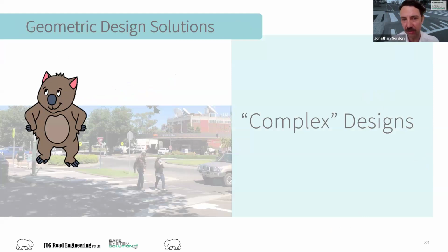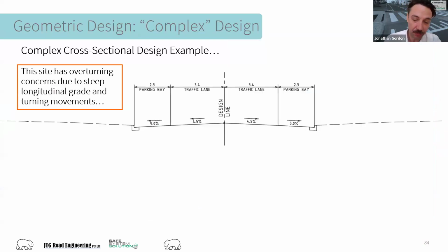We're going to have to change our longitudinal grade or our cross section to make this project work. That's when things get a bit trickier, but most of the time we can resolve these issues. And occasionally, as I've mentioned, you might end up with a feasibility issue for a site, and you might need to re-strategize your solutions or your path networks if you cannot get a site to work. But it is rarer. It just often depends on how much money you have to spend to solve the solution,